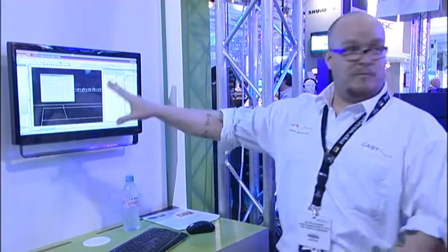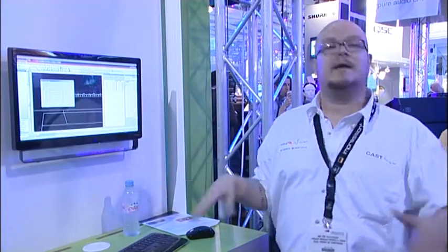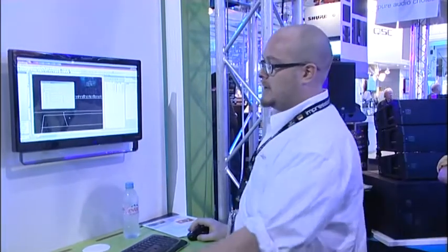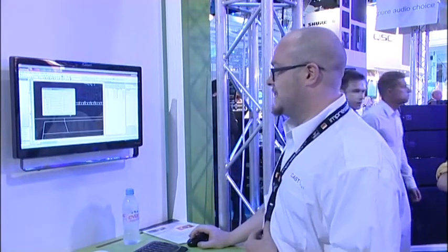Just need to look at attributes of a fixture, pan, tilt, focus, things like that. You can, very fast. And the fixture window now is non-modal, so you can keep it anywhere you want it, and it's always moving, always working. We've also added the ability to quick tool or quick fixture lamp and lens types, which saves many seconds off of operations in Wysiwyg. This is very important. I keep stressing speed. That's what we're stressing in this release.